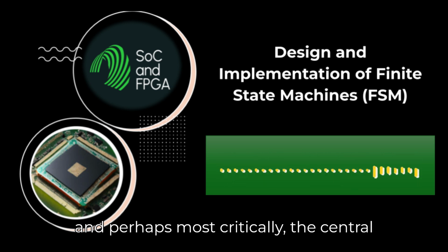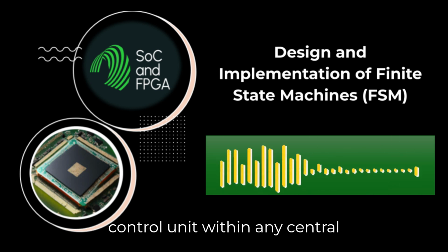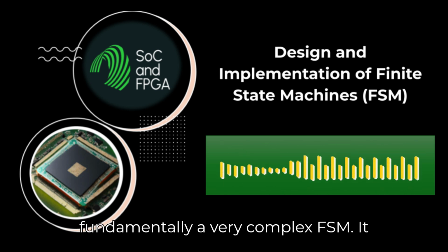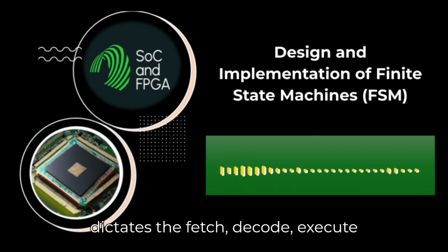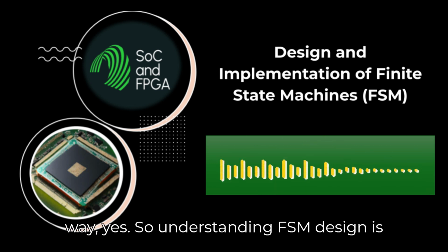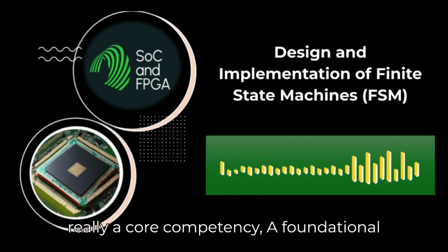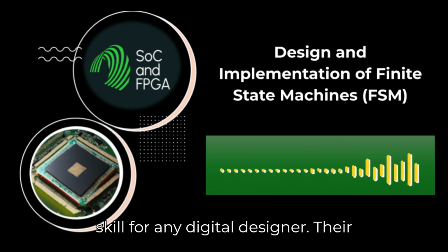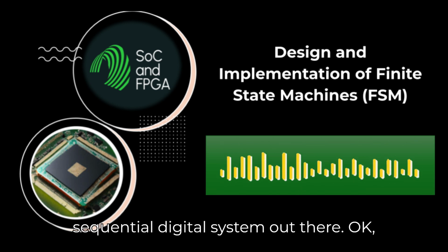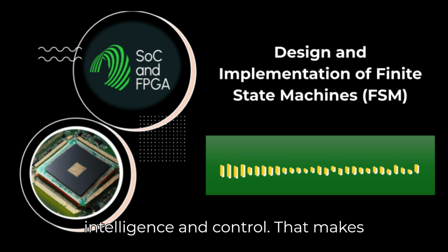And perhaps most critically, the central control unit within any central processing unit, the CPU. That's fundamentally a very complex FSM. It dictates the fetch, decode, execute cycle. The brain's brain, almost. In a way, yes. So understanding FSM design is really a core competency, a foundational skill for any digital designer. Their principles underpin virtually every sequential digital system out there. Okay, so FSMs give our systems their intelligence and control.